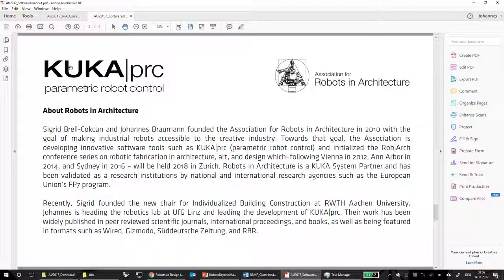About controlling external devices, a big change for us is, of course, 3D printing, more for smaller robots, where we can very quickly develop tools. But the interfacing is not particularly complicated. If you want to send signals to some kind of external extruder, you use this kind of bus system, for example, and they're also used, for example, in home automation. So if you're lucky, you can go to your local electrician and he actually knows how to set these things up. These are not highly proprietary robot stuff, but more general automation technology that you can find in many places. So that makes it definitely easier.